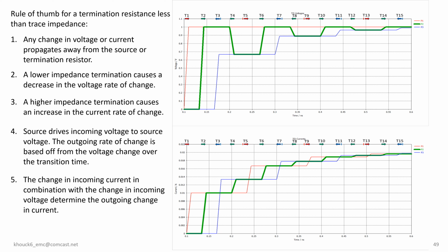At each marked time interval on this slide, we observe voltage and current measurements taken at three significant points along a trace: the drive, midpoint, and termination. These distinct time markings symbolize the progression or traversal of the changing field wave along the trace. The red line and arrow signify the drive source, symbolizing where the signal is initially injected into the trace. Meanwhile, the green line and arrow denote the midpoint of the trace, offering valuable insights into how the signal behaves as it travels along the trace.